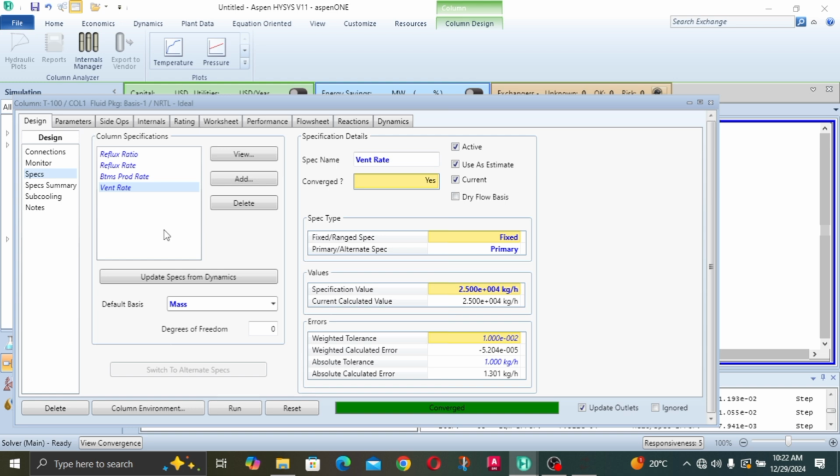If you talk about boiling point temperature, it's relating down to heating or cooling. But in our case, we do not specify the temperature, and we do not have heaters. We do have a heater, which is the reboiler doing the heating, but we cannot alter the reboiler because we did not specify the temperature. That's why we're currently on specs. We will be altering what we specified ourselves, which is the vapor rate. Basically, the amount of vapor we have at the top.